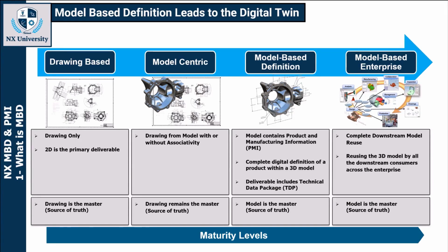Going over to the far right here, the model-based enterprise setup, that's going to complete our downstream model reuse. So we're taking that physical model that has the embedded model-based definition PMI on it, and we're going to reuse that 3D model by all the downstream consumers across our enterprise. The model is the source of truth, and if something changes on this design, this model, all the PMI is going to update accordingly, and that will propagate downstream to the other operations at the enterprise.